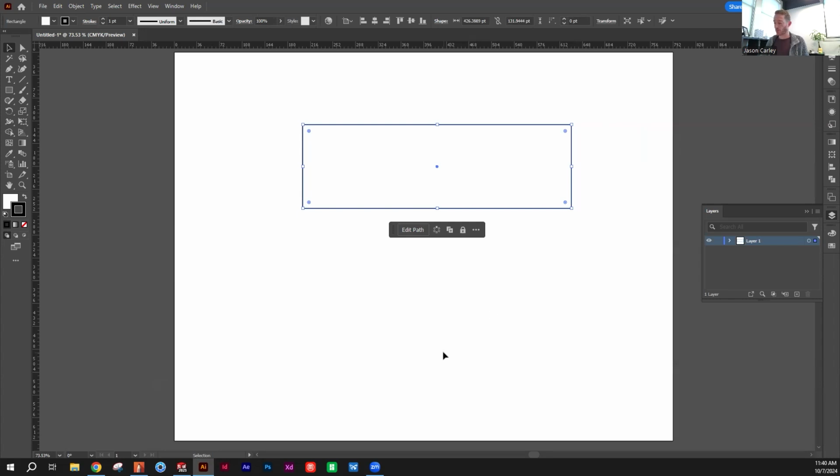So jumping back into Illustrator, I can set these to be, if not dimensionally accurate, I can at least lock the proportions to what a shipping container might actually be. So I know from doing a little research that usually they're 40 feet long. To bring that into Illustrator, I can use simple mathematical equations. So I could take 40 for 40 feet, and then the asterisk for multiply, and then 12 for inches. And if I hit enter, it gives me 480 points. The points doesn't really matter as long as you're consistent in your coordinate system.